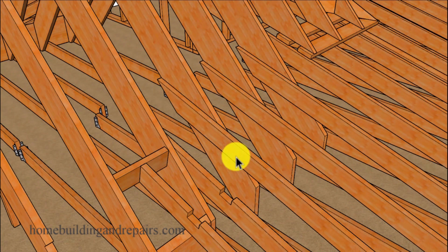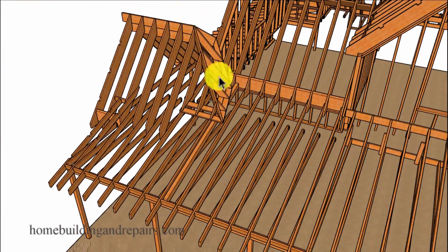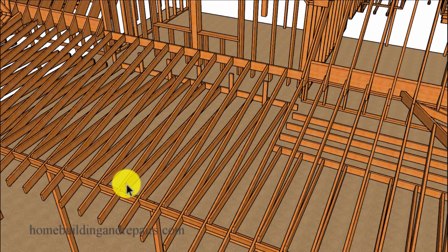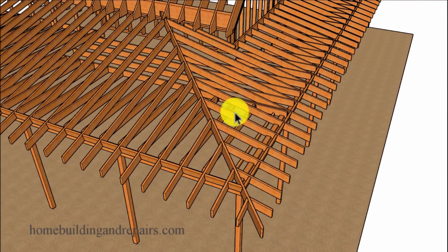And of course, the porch rafters will be connecting to the roof rafters here that will be sitting on top of a wall, a short wall. And I would imagine after you finish building something like this, you could consider yourself to be a roof framer. And the porch is going to be a little bit longer in the back, might require larger rafters, and you might need to install larger hips or double up the hips or add some type of structural supports in the areas where the hips are going to be sitting over some type of load-bearing walls.